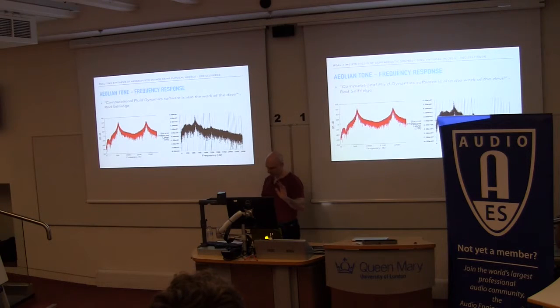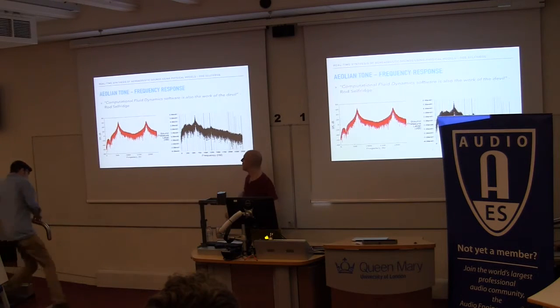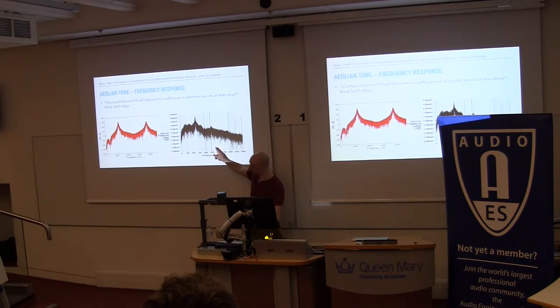Two different plots here. This one is my model. This one is a fluid dynamic software package called Fluent. The wind speed is 42.67 meters per second, and the diameter of the cylinder is 0.0127 meters. Okay, it's two-dimensional, azimuth is 0, the elevation is 90, and a distance of about 12 meters. But in fairness, the gain is not really as relevant as the frequencies.